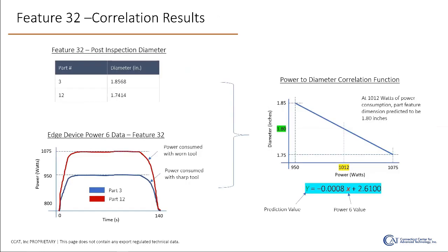And these are the results. What we did was we collected data using a Siemens Edge device. It was connected to the controller, which happens to be a Sinumerik 840D SL controller. So we were able to grab a high frequency stream. The data collection rate was 500 Hertz. And in fact, we're able to collect up to 100 parameters. In this case, we're only looking at spindle power.